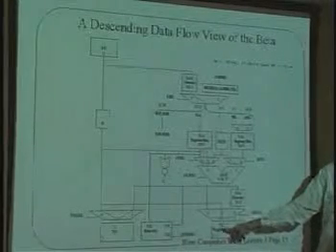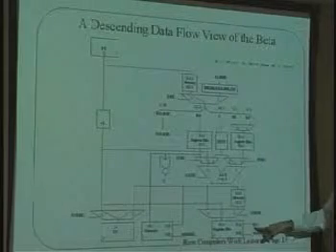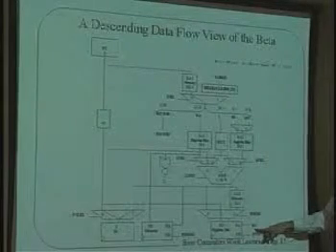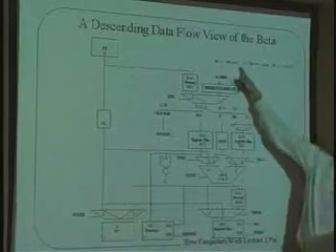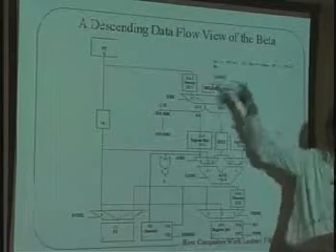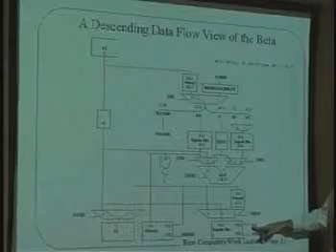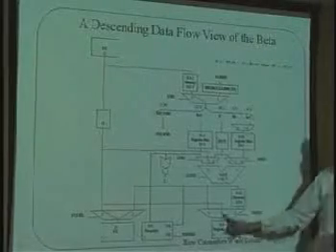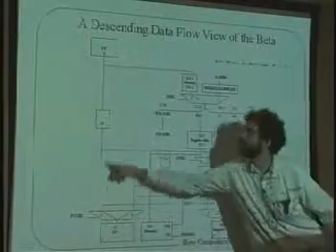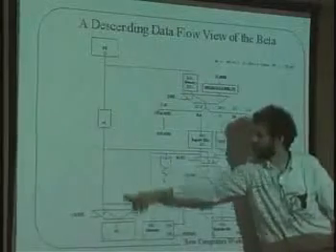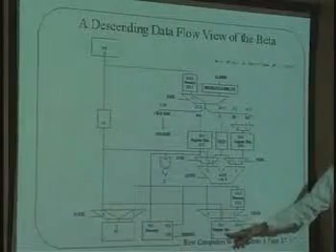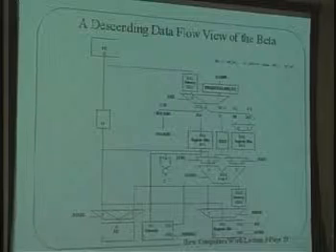Now, which register will get written? The one indicated by register C. And so this is the way that we implement the first part of this instruction, which is remember where I came from. RC gets loaded with the contents of the PC plus 1. And that's happening along this path right over here. PC plus 1 goes into the register file written as RC.